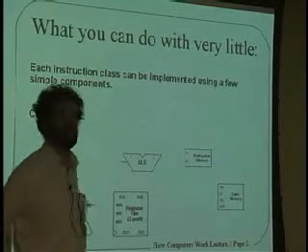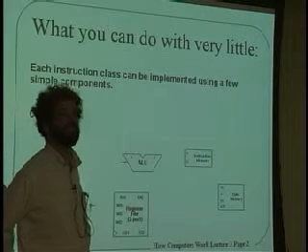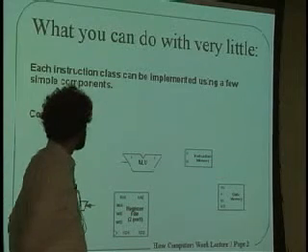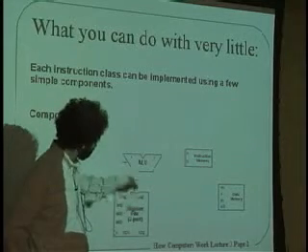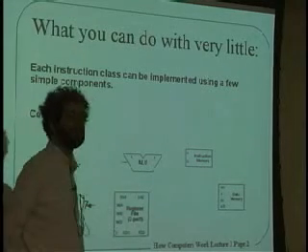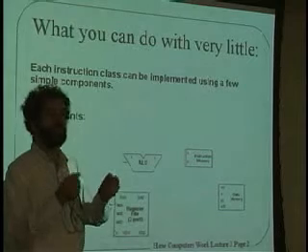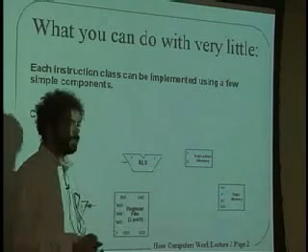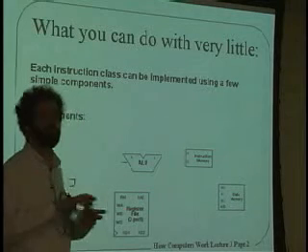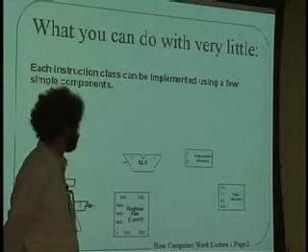Except in the case of register 31, it'll have a pretty easy time because it just throws out the bits and produces a 0. But that register file is going to have two paths for doing reads, because we'll want to read two registers at the same time to combine them in some kind of operation, and one path for doing a write, which is going to be used to write the result back to one of the other registers.